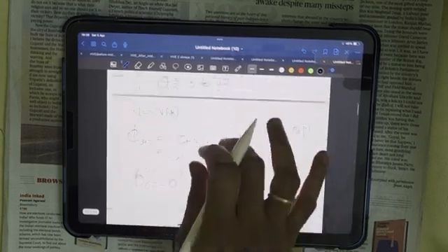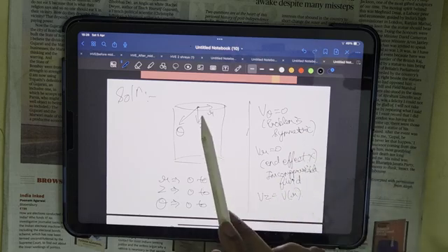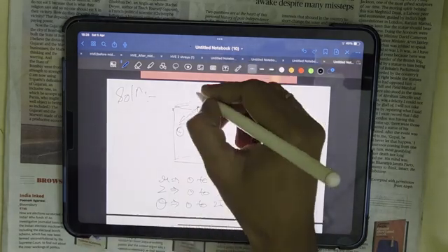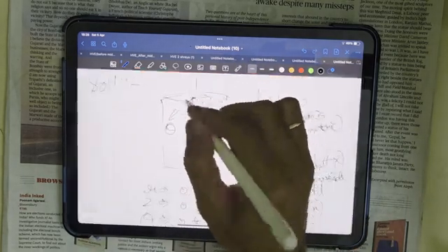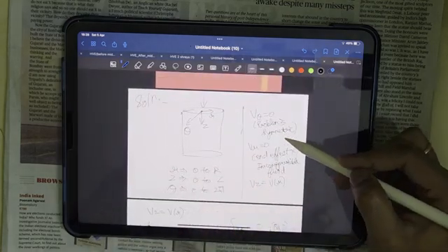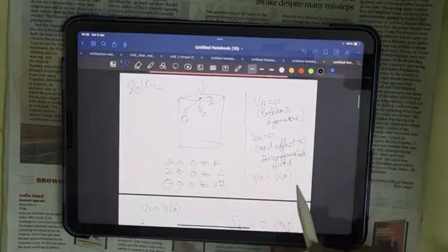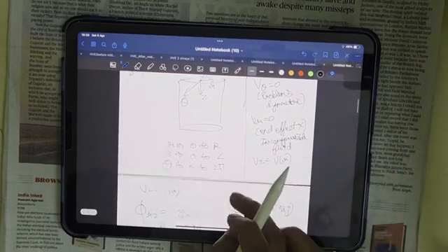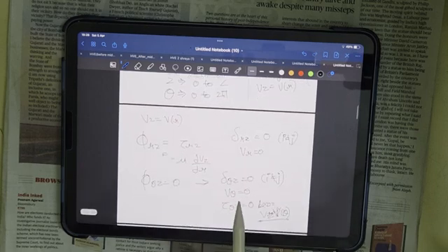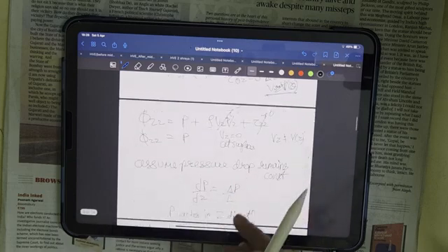Summarizing the problem, we started with the Cartesian coordinate, then chose the coordinate as cylindrical coordinate. Vertical tube, the flow is downward. V theta is 0 because the problem is symmetric. VR is 0 because the end effects are neglected and the fluid is incompressible. Vz is a function of R. R varies from 0 to R, Z varies from 0 to L, theta varies from 0 to 2 pi. We find out the non-vanishing terms, and the final equation which we got is this: